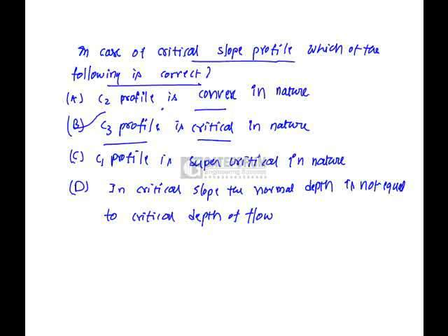C1 profile is supercritical in nature. No, it is not supercritical, so this is not correct. In case of critical slope, the normal depth is not equal to the critical depth of flow. This is also not correct. So option B is correct.